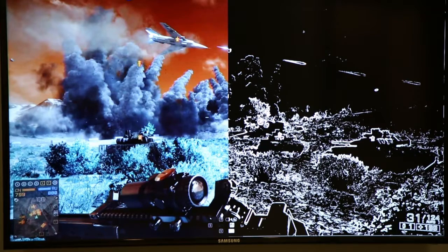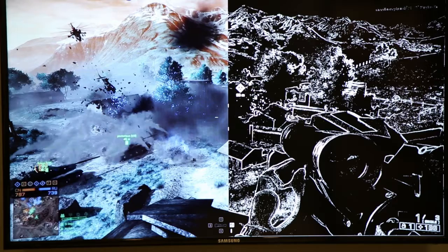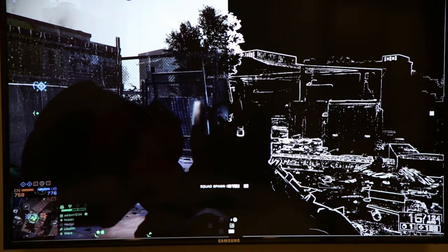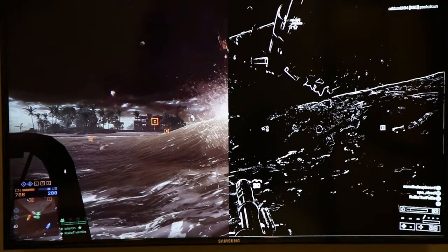Here's the design actually running on a Zynq 702 development kit with an HDMI FMC card. As expected, the processed image is refreshed almost every 10 seconds. However, this shows how easily you were able to get a complex Zynq design with 3 hardware functions using C only. Now, you can focus on optimizing the Sobel filter to improve the overall performance.